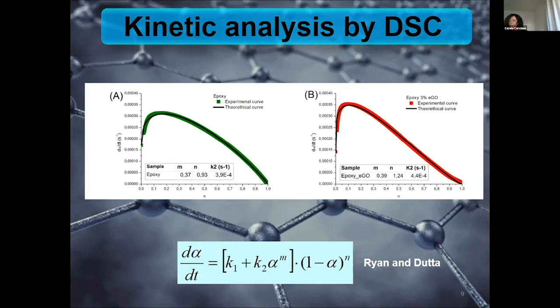And so it is a very important result that we wanted to study not only by DSC but also by rheological studies. In fact, another important consideration is that at a higher rate of reaction, the specific volume is farther from its equilibrium value. And close to the end of reaction, this corresponds to a more rapid decrease of the rate of reaction, as a consequence of the vitrification driving the reaction to its end. So the rate of reaction decreases faster when N is higher. And this is also evident from the last portion of the rate of reaction curves shown in this slide. So I think that this observation needs to be confirmed by other techniques.